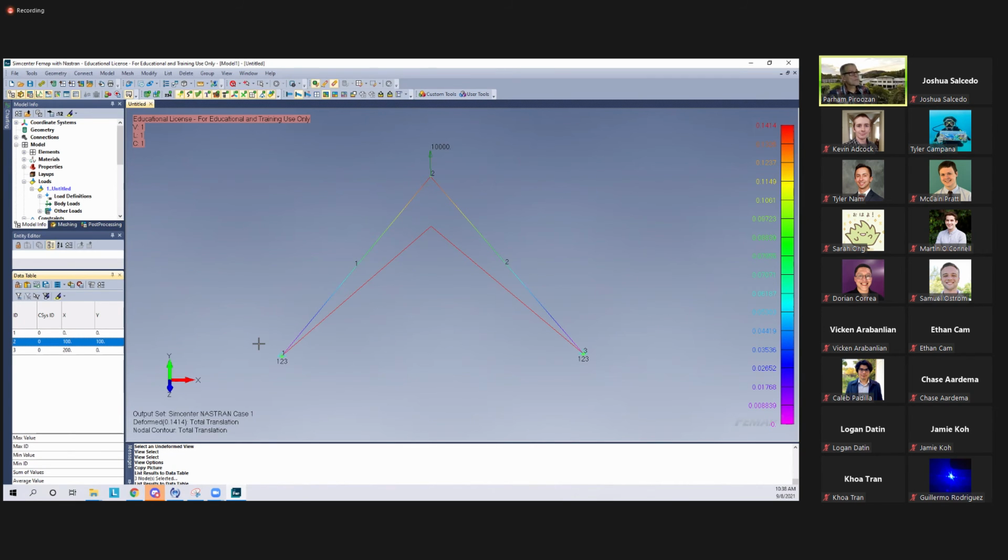So you could put deformation of element 1 and element 2 in that table as well? Deformation, not for elements. Deformations are for nodes. Oh, okay. Displacements are for nodes. But an element is continuous. At what point in this element do you want the displacement? The displacement of one point is given. So these are nodal displacements. But for elements, it is stress or force in an element, not displacement. Right. Okay. All right. Any other questions?